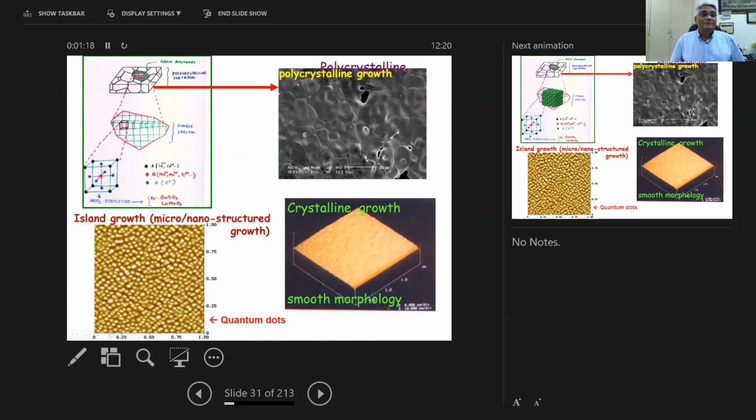And here on a 1 micron scale, you see how many of these small regions there are, right? So this is a perfect example of the formation of quantum dots. If you go down to this level, between 0.25 and 0.5 microns, and you look at that block there, you can count how many are there, and we can estimate the size to be anywhere from 50 to 70 nanometers.